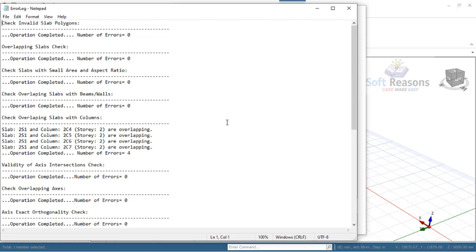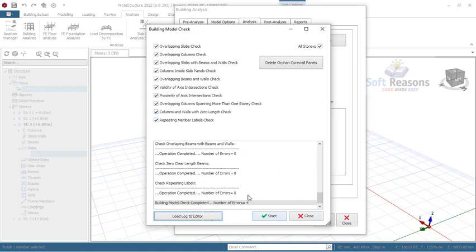You know, the column drop and the top of platform of the tank, they are overlapping. That is where we are having this overlap, but you cannot do anything about it because it's not going to interrupt our analysis and design. Okay, so that is not an issue. Assuming we have a beam there, it won't have been showing this overlap, but it is because we do not have beams there, so we are designing it as a flat slab over there. Okay, so close that. That's why you are seeing this error. All right, so we close this window as well.